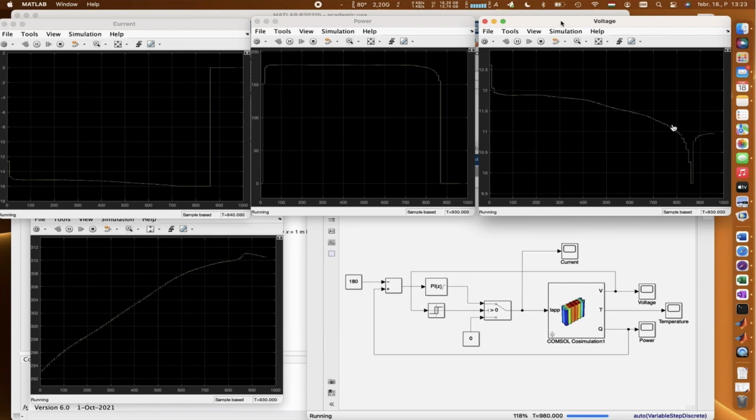So you can test your PID controllers, your algorithms, what is happening here around our model, and you can combine both worlds. You can have a high fidelity model with a finite element modeling of the batteries, the battery packs, so you can have multiples of those, and you can test your control algorithms, what kind of management you can achieve with these setups. What will be the maximum temperature? Do you need an active cooling, or maybe the current setup, this passive cooling setup, is way enough? So you can test different scenarios for different cases.